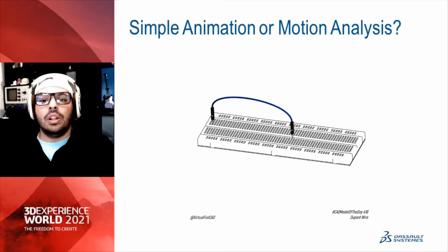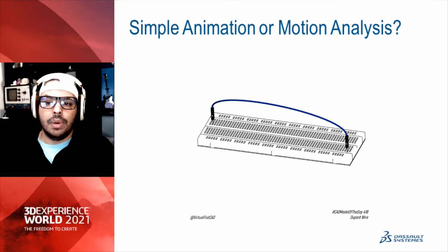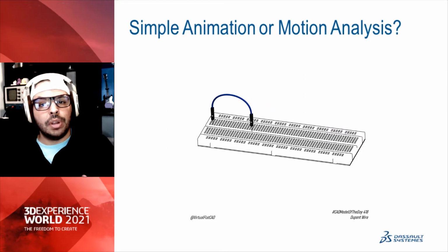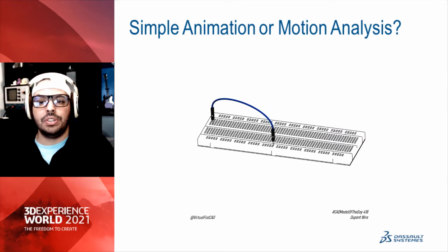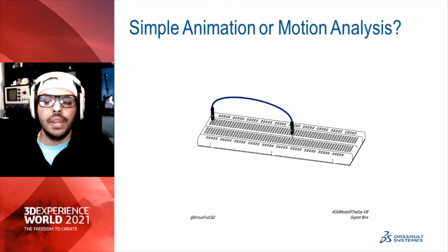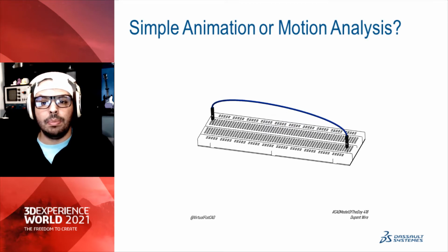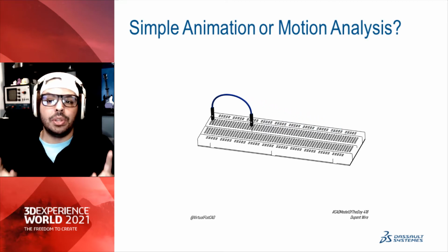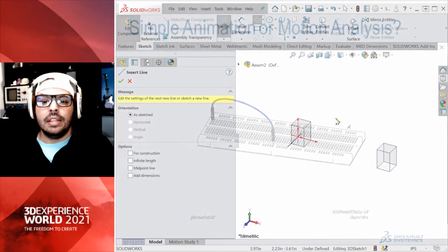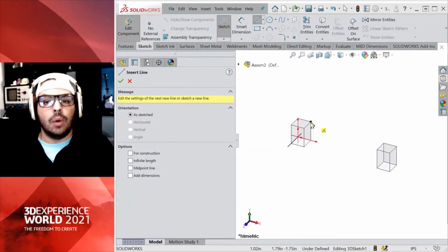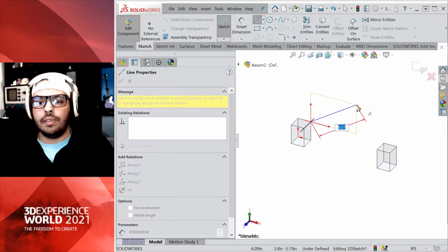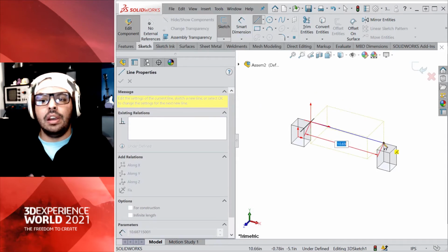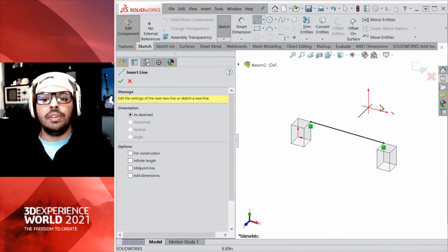We need to recall another function of SOLIDWORKS assembly modeling. We can actually construct part features based on the size and position of other parts in a shared assembly. This is called top-down assembly modeling if you want to know more about it. But the real question is this. Let's say I draw a spline and say that one end is coincident to a vertex of a part, and then say the other end is coincident to a vertex of a different part.